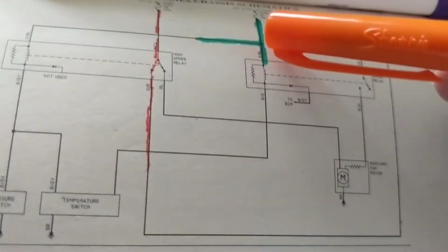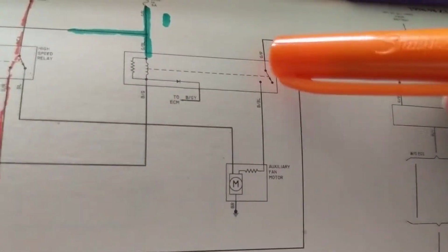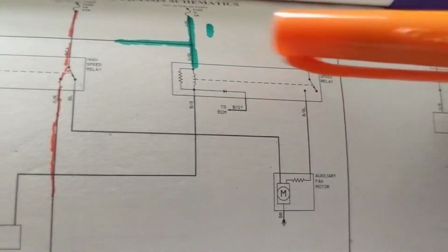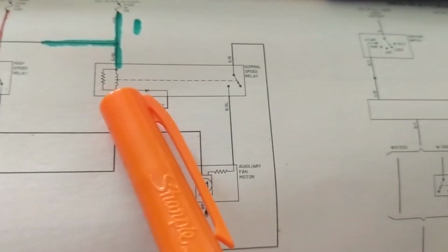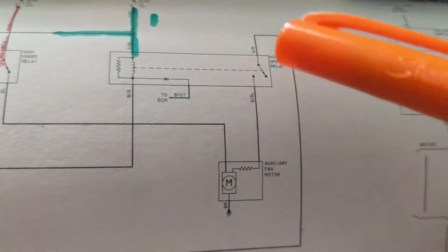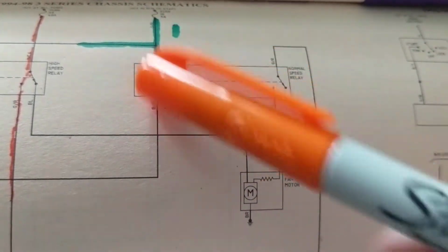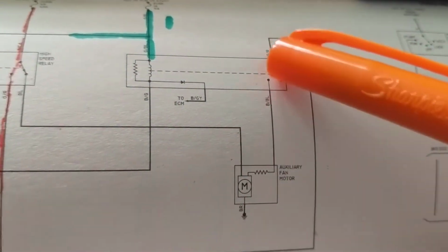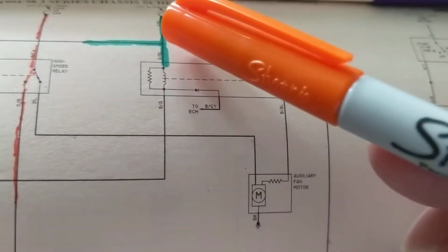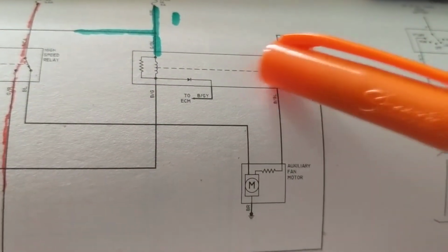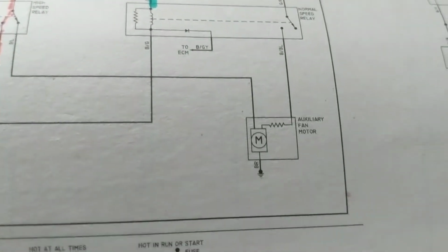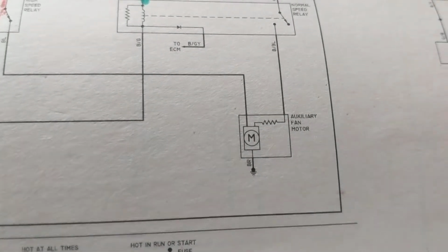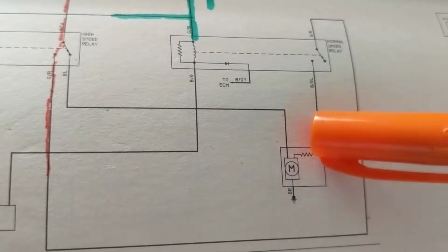So first you always look for the coil part of it. Then you go for the switch part of it. Again, current has to flow through this. Again, we see the same sequence. A dotted line. This is at rest. This means there's no current flowing. There's no activation, no magnetic field. This will be in that position. When the coil is activated, this is pulled in. So now this one will go to this one. So, as you can see, it's almost the same circuit as before. However, let's try to analyze an automotive circuit.